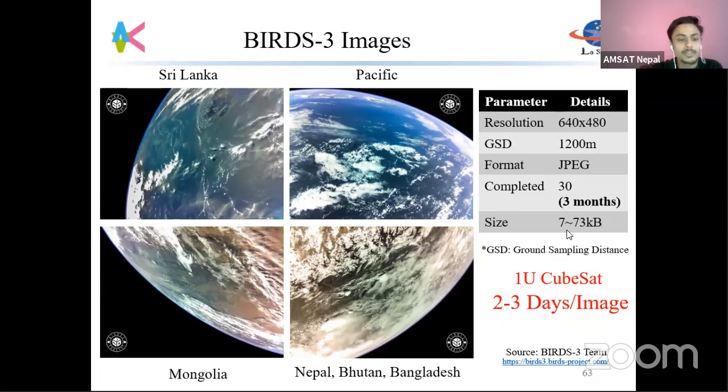Okay, so you talked about the packet loss in the last question. My other question is, can we send the missed packet again and again to improve what we missed? Yes. What we do is, we know which address the missed packet is from. It's all about the flash memory address, right? So the way we send a command is, hey, give me the file that's located at this address, and then it gives us the data. Once we get the data, we look and see that a packet is lost, then we know which address that packet is lost from, and then we command it.